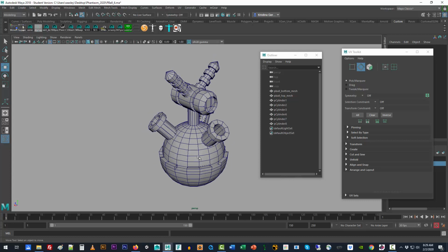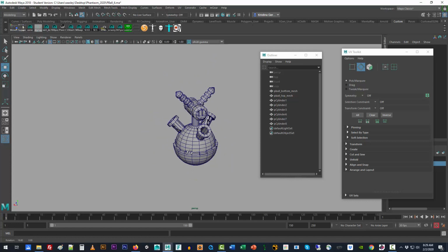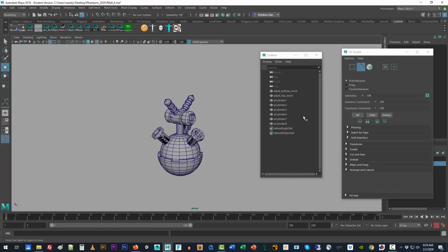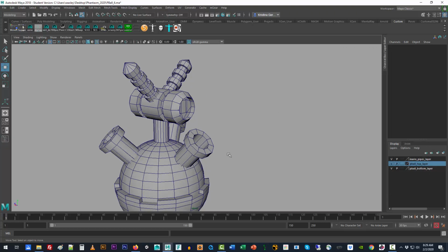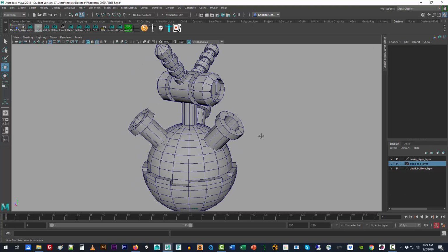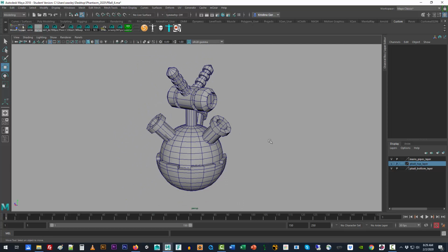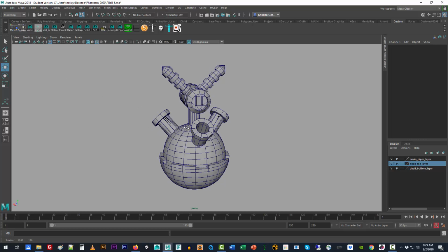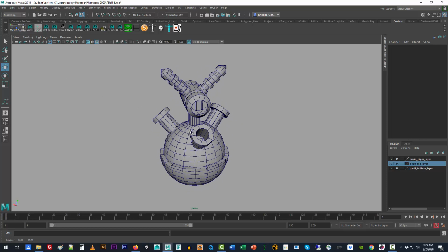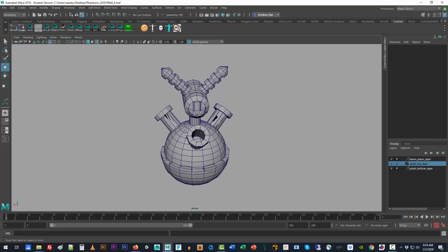By the way, what I have here is a little bit of a drawing issue. You see the way that that's jittering? That's because the Maya camera that's drawing things has a field between a certain point to begin and a certain point to end. And this jittering is usually indicative of having my camera way too close to the beginning drawing plane, way too close to the camera.